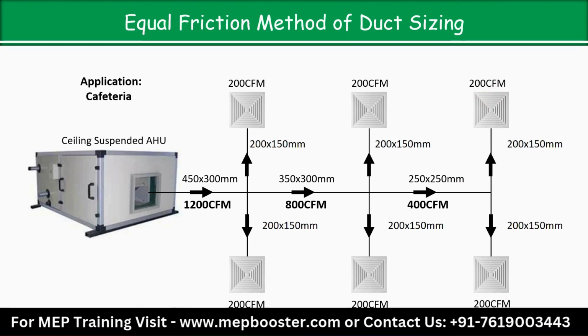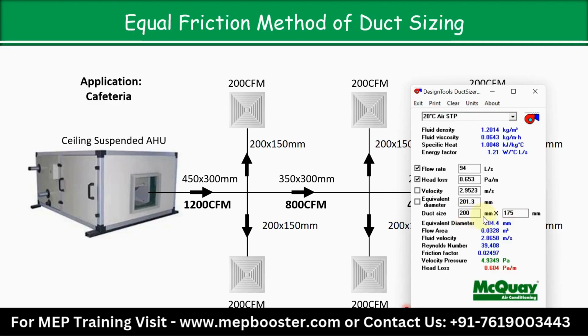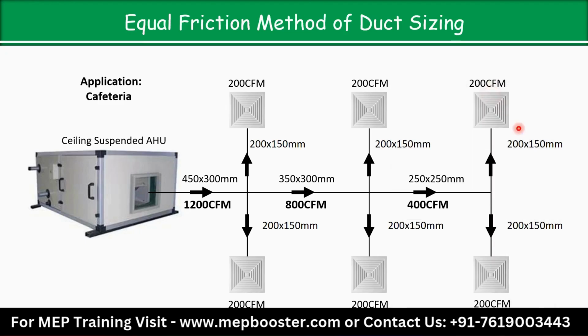200 by 200, or you can also select 150. Right now we have selected 150 height, so you can go for 150 also. It depends on you, otherwise 200 by 200 you can also select. I'm going for 150, so for 150 you will get near about 200. It depends on you, but you have to remember that the branch duct height should be less than whatever height you have taken for the main duct. In this way we have to do the duct sizing as per the equal friction method.